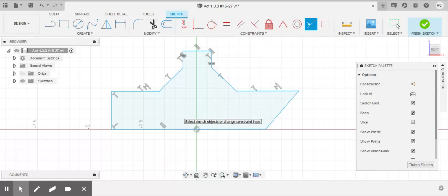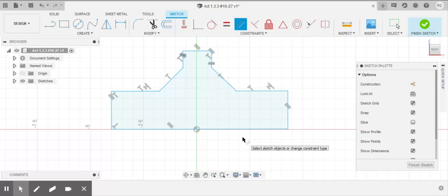Okay, and then the last thing I think we have to do is I want to make this one parallel with this one over here. So let me click on parallel, make this one parallel with here. There we go. So now it looks pretty good. Okay. So now, if you notice, if you look down at number 20, next for 21, it says to create a quick sketch of the profile and show the constraints that you added. So pause right now and make a little quick sketch on paper and show the constraints that we added.